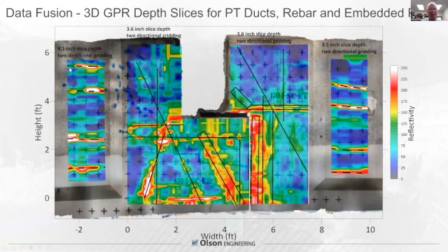So now we're able to track these features showing where the ducts are, these stronger, brighter reflectors. The next thing that's shown on this is the thicker 20-inch section, and we did scan with radar from both sides because it can penetrate approximately 20 inches, but you get higher resolution if done from both sides.